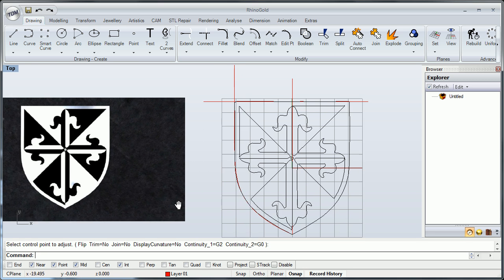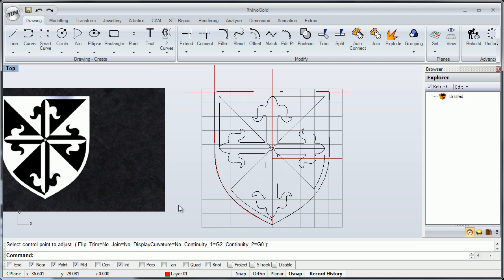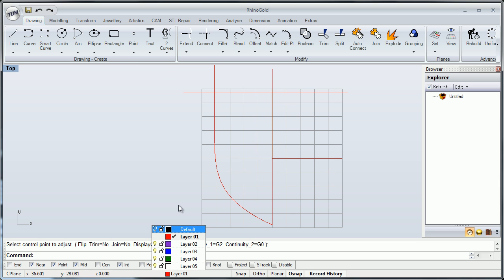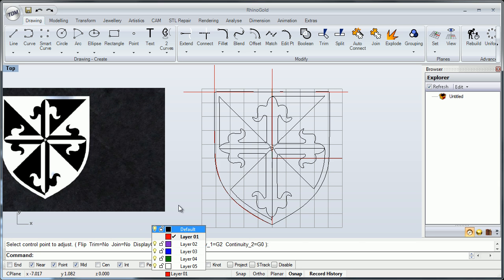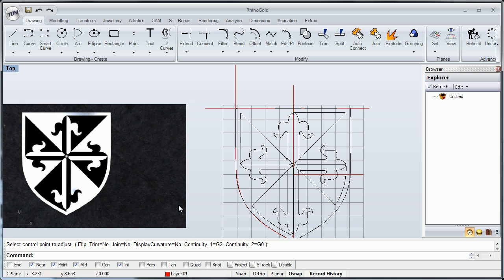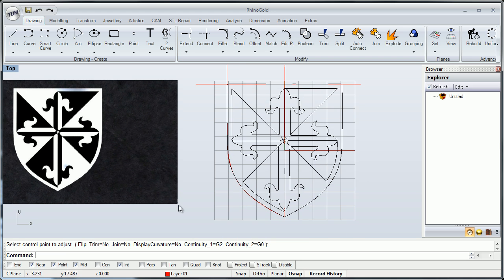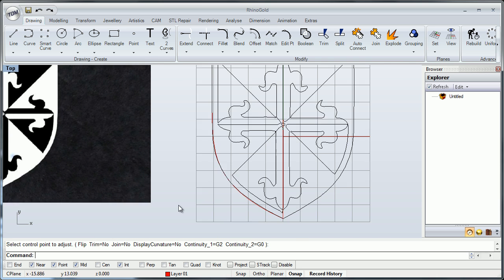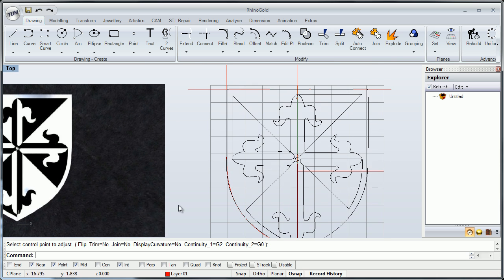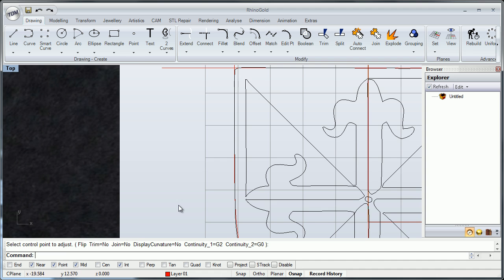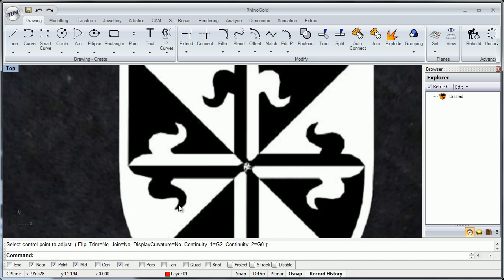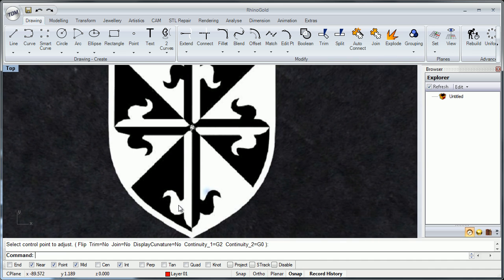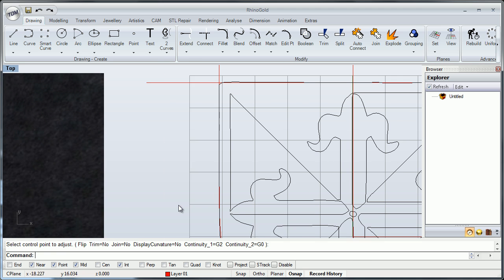Say okay, great, and now we have this curve. The idea will be just create half of the piece and later we do a mirror, and that's it. Okay, great. Then let me create this curve. It looks parallel, so we have an offset. Let me analyze what the offset is.